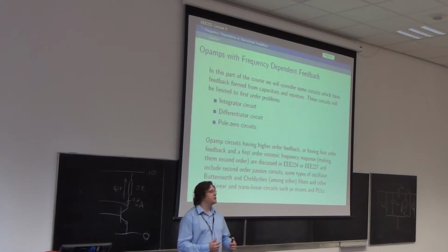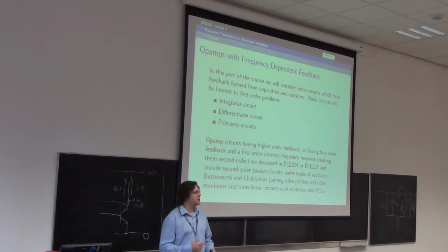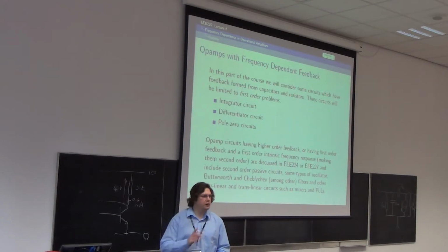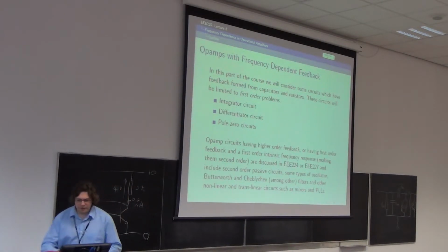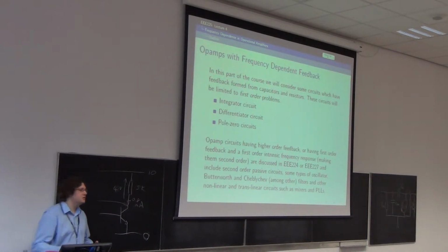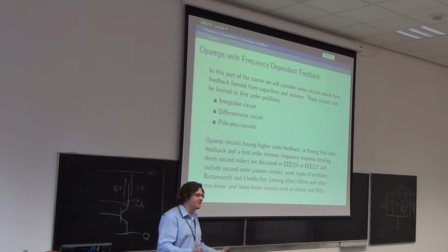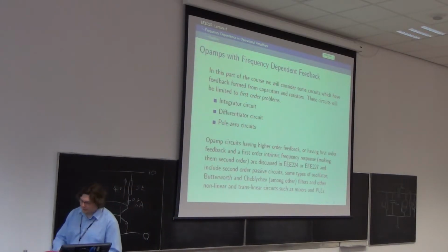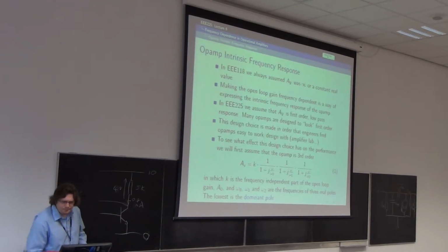If you want to stuff them both together, you'll end up with something second order. If you've got a second order circuit and an op-amp with a first order response, you'll end up with something that's third order. The orders just add up. So only first order stuff here, second order stuff elsewhere. But that does not mean that you ought to try to compartmentalise them in your mind differently. It's all one glorious whole of electronics.